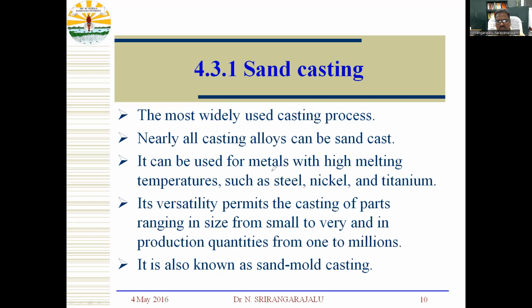It can be used for materials with high melting temperatures such as steel, nickel, titanium, etc. The versatility permits the casting of parts ranging in size from small to very large, and in production quantities from 1 to millions. It is also known as the sand mold casting process.